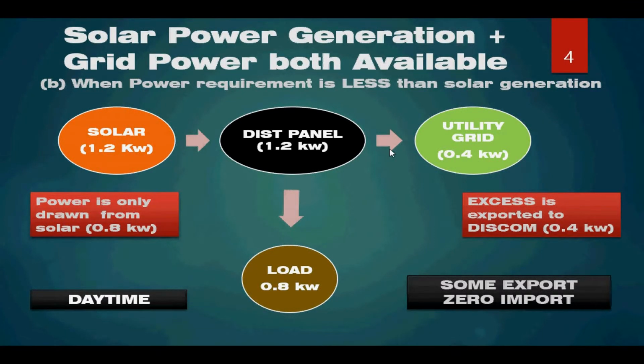The net meter will measure the current flowing in the opposite direction separately under exported reading. So in this case, we are not taking any power from the grid, but instead we are exporting. This exported power can be used in future when we need power from the grid, like in case A.